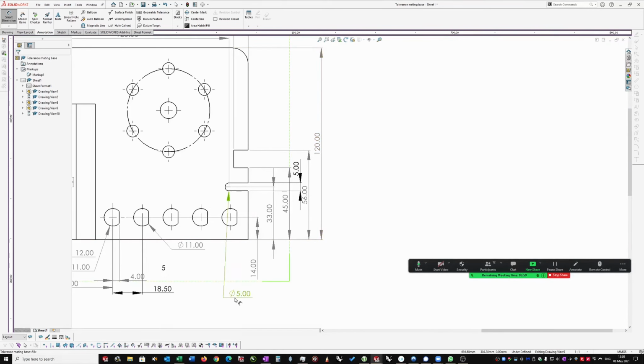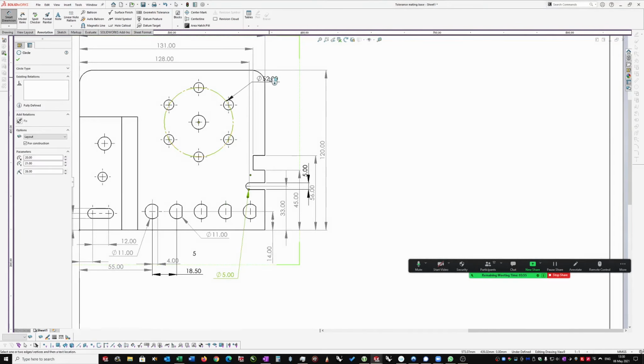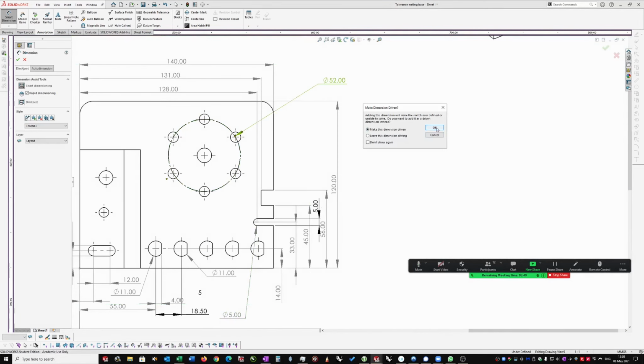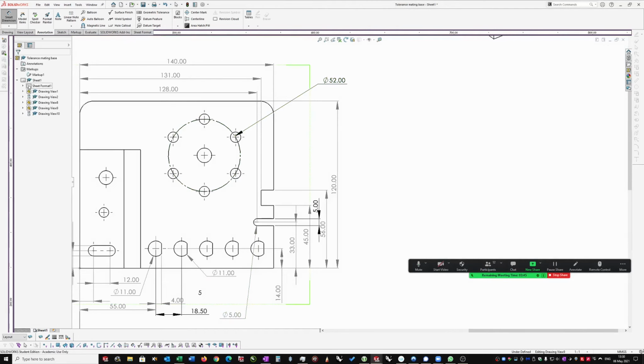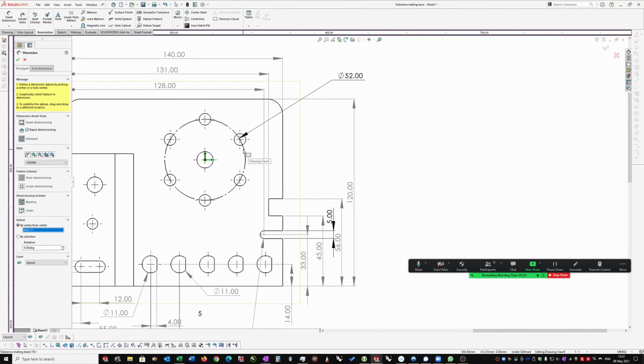Right, and so there was one other thing I need to show you here, if I can remember what it is. Let's just dimension this quickly and see. Down to 5.2. Yeah, now you really should be able to use this Feature Manager. Dimension expert, sorry. Polar dimension. That's what I'm not doing. Okay, so you got to select the center of the feature first. It's very difficult to see even for me. It's that axis, and then it's this feature.